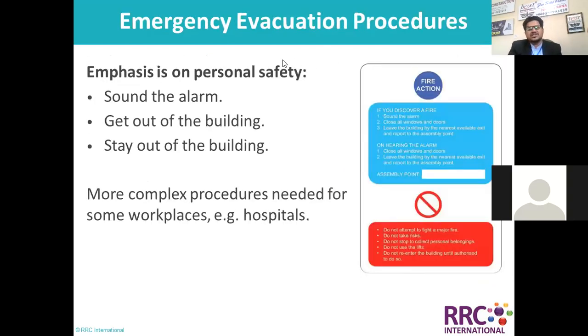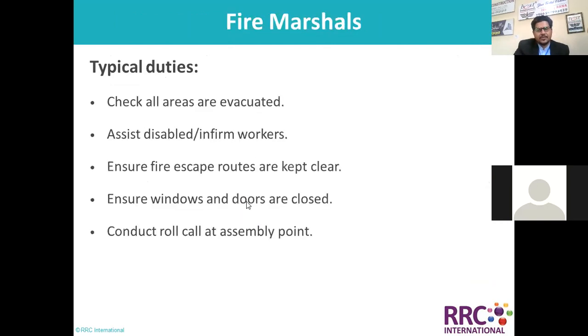Because there must be an emergency evacuation procedure, and that should also be tested: sound the alarm and get out of the building, stay out of the building. And yes, more complex procedures are needed for some workplaces like hospitals. Fire marshals have typical duties like checking all areas are evacuated, assisting disabled or infirm workers, and ensuring fire escape routes are kept clear. So you have a firefighting procedure or fire safety management procedure.